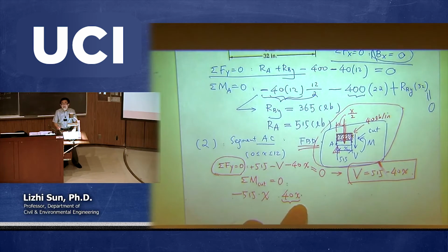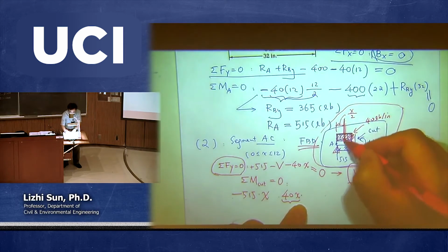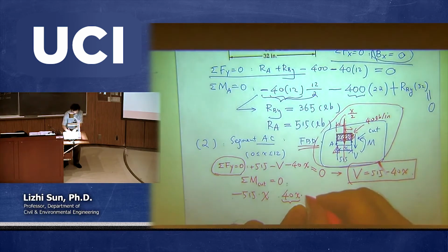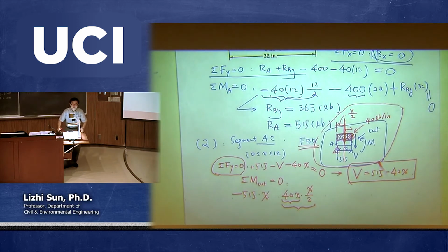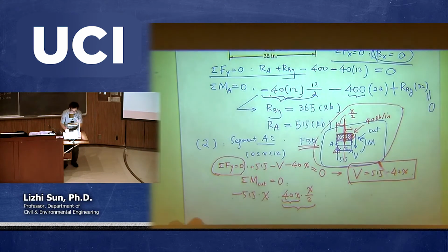It needs to be multiplied with the shorter distance. The shorter distance is from the point you want to calculate the moment about to the force line, which is this. So that's a half of x, because that's a local center. Half x. So altogether this forms the moment of that force about the cutting point. And this is going to be counterclockwise at that cutting point.